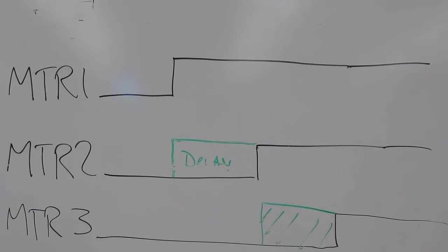I mean, that's the big key to making the shutdown process work, is enabling the off delay for motor number 2 by motor 3. Off delay for motor 3 by motor 4. Now, is there an off delay for motor 6? No, if they're all running and we hit the off, motor 6 stops immediately, right? So there is no off delay for motor 6. Bam, it stops immediately. But then since motor 6 is stopped, the off delay for 5 is enabled and it will start counting down. And then motor 4 counts down. Motor 3 counts down. Okay?